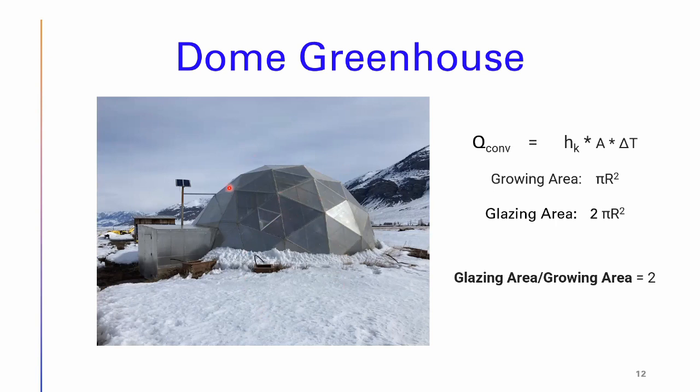But this, I insulated the north side with polyisocyanurate. And what I want to point out with this, more math, is if all things are the same, if your relative humidity, your temperature, your wind velocity, if you consider all that is the same, and you look at this convective relationship, this is Newton's law of cooling, your h sub k value is going to be your heat transfer coefficient. And you can lump both the convective and radiative portions into that h sub k value.